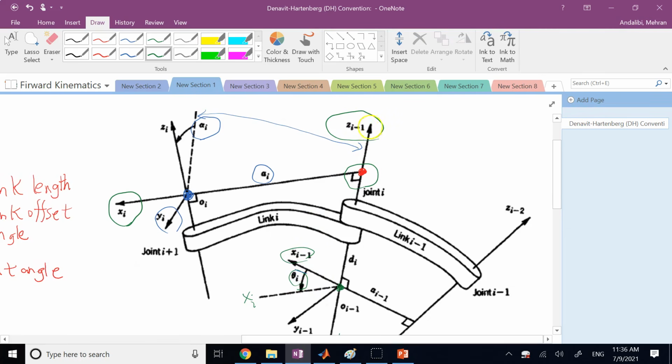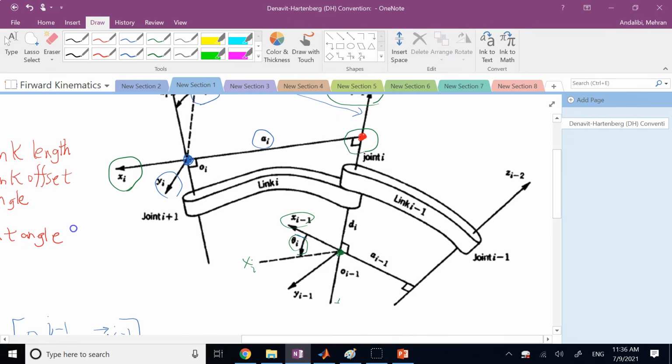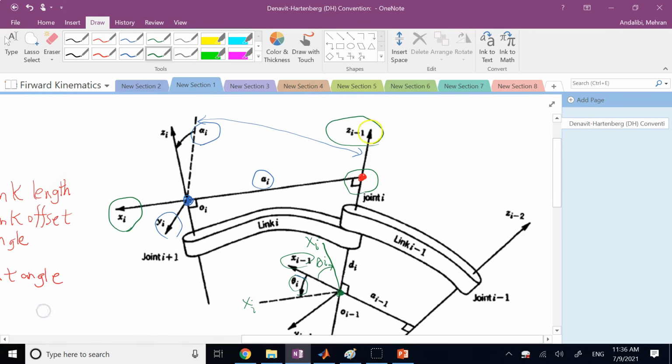If this rotation theta, for which you can determine the direction using the right-hand rule, correct, is the direction of rotation of theta aligned with Zi minus 1 or opposite to it? In this case, you see Z is upward. This theta looks like counterclockwise about it, so it is positive. But if, for example, Xi was here, so I had to go like this to align it, now this theta i about that Z is going to be what? Negative.